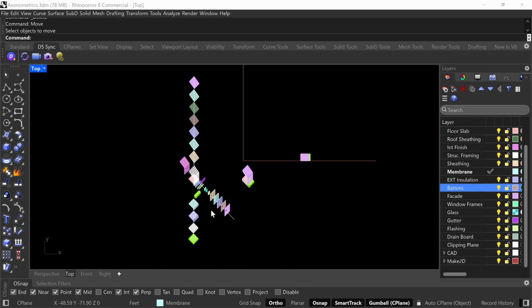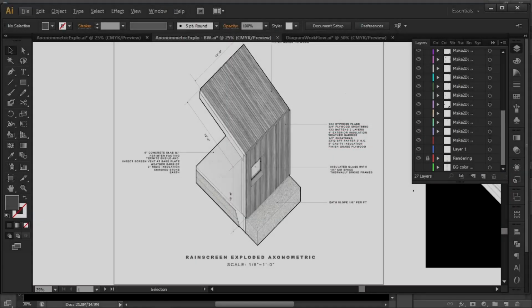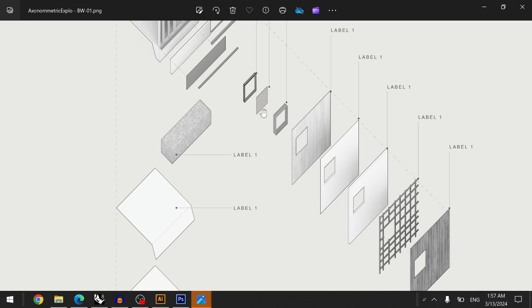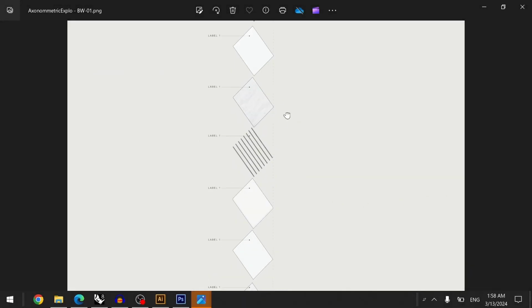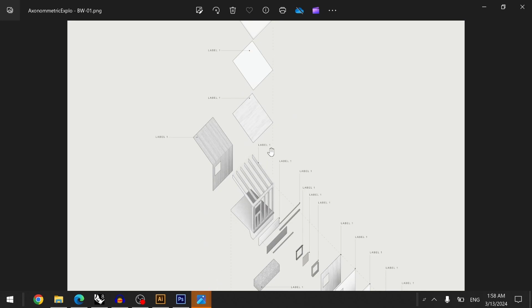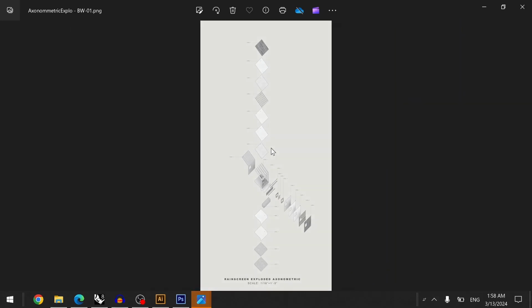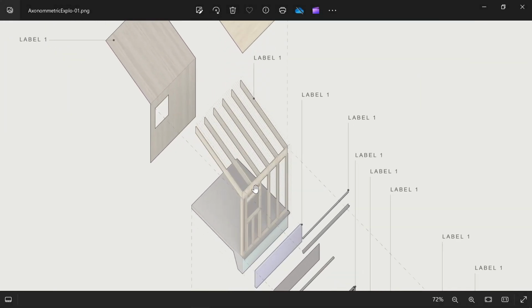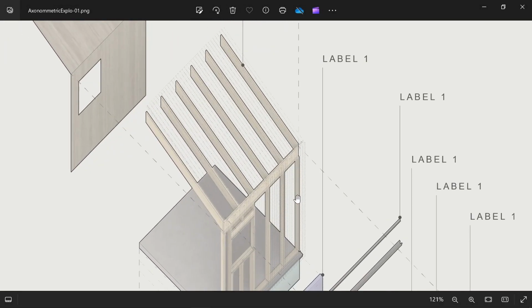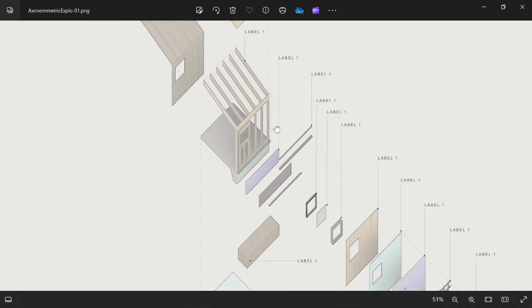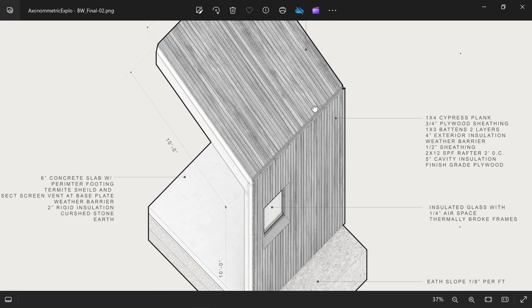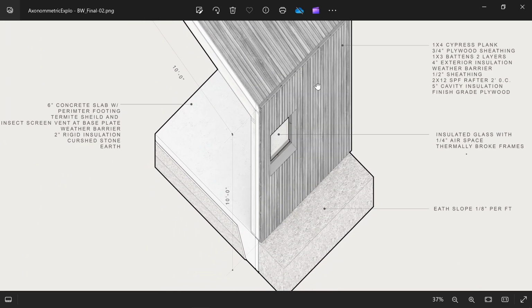So in this video course, we're going to cover true length axonometrics, meaning that when you make 2D your axon in Rhino, you will get the true length measurements. And so we're going to do an exploded axonometric in Rhino, and I'm going to show you the workflow of how to show different types of exploded axonometrics, both from a 2D standpoint and from a rendered exploded axonometric option as well. So let's just go ahead and get started.